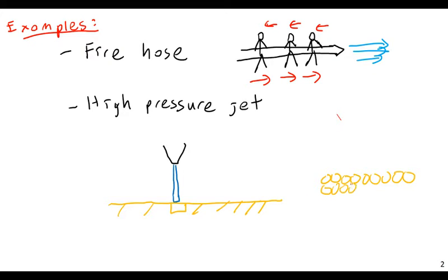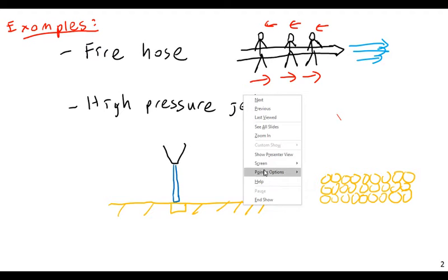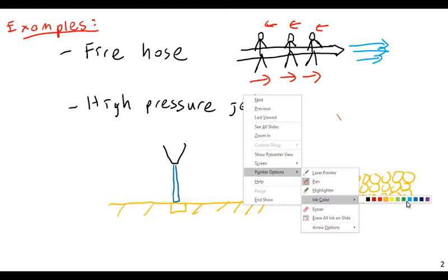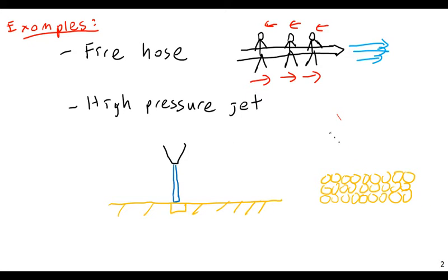The only way you can break a bond is by supplying energy. With a cutting device like a blade, it's a bit more complicated to explain. It's more like one crystal structure is forced against another crystal structure, and that causes cleaving along slip planes and things like that. But here, you're using a direct momentum exchange type of process.